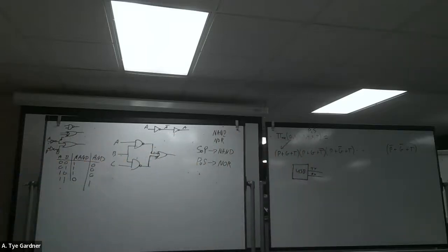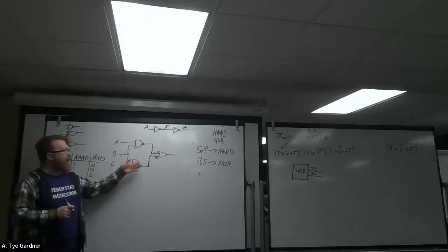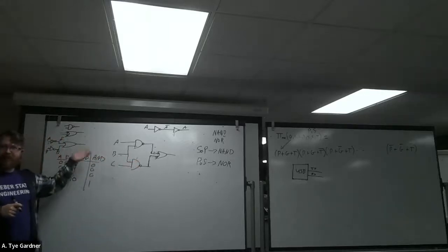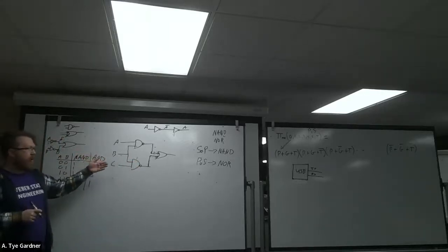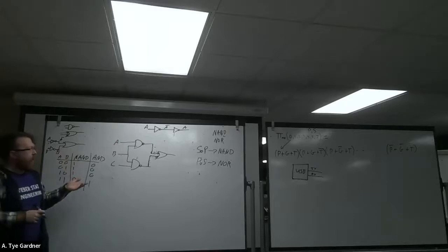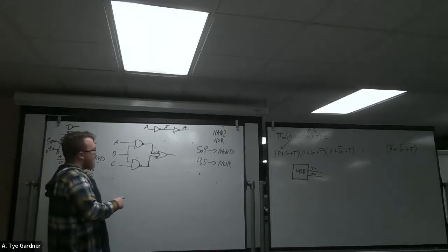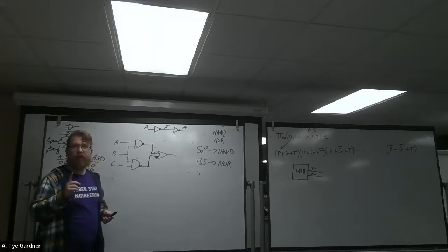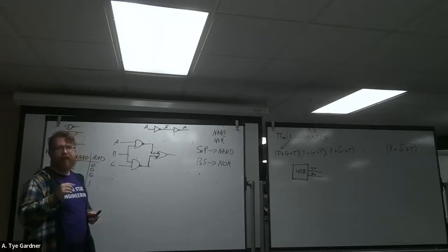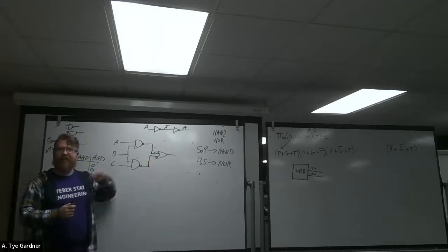Okay. All we really did was just switch the OR to a NOR and two ANDs. Yeah, but think about it as bubble pushing, because I might give you 2-layer circuits, because those do happen, and all you're going to do is just push. And what's nice is, you start at the far right, as far as you can go, and you just put 2 bubbles at the input of the far right gate.